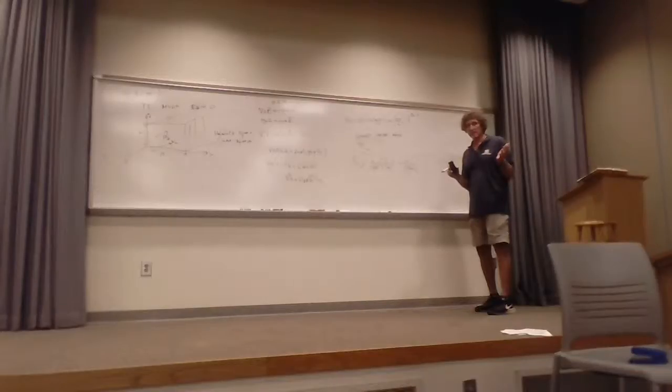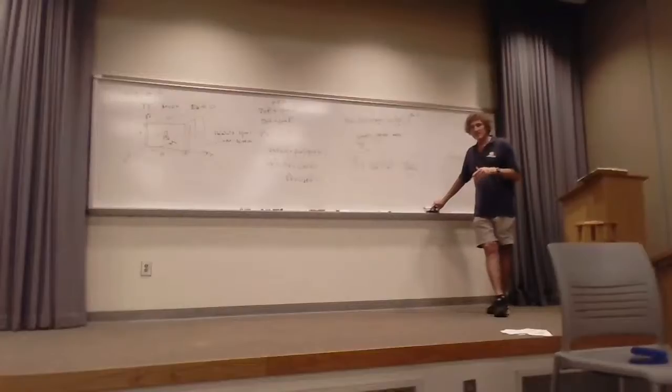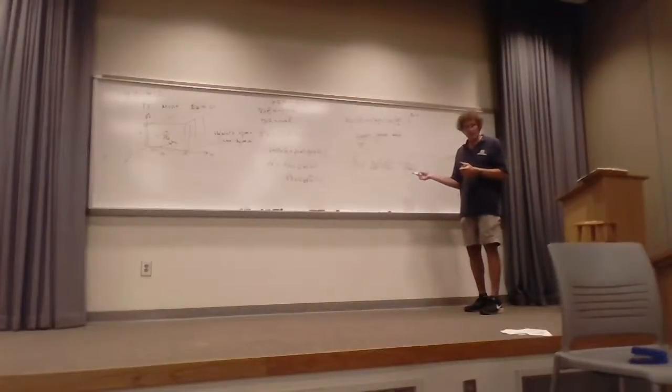Good on that, guys? Now here's the deal. The way rectangular waveguides are always designed, the first frequency that will propagate will be the 1-0 mode. Then the second frequency will be the 2-0, and then the 1-1. And the reason they do that is this. See, that's the 1-0 mode, right? I'll show you how they do it. I want you to get a hold of everything I'm saying here, because the last 15 minutes of class are going to be real important.